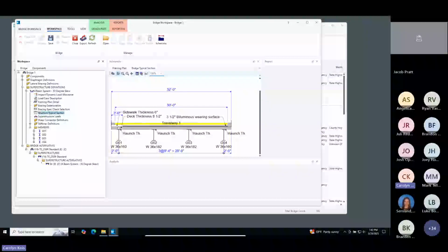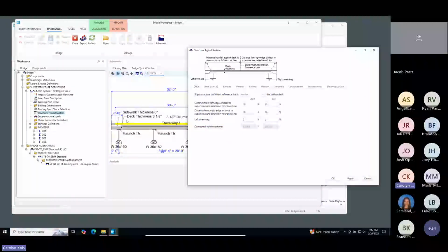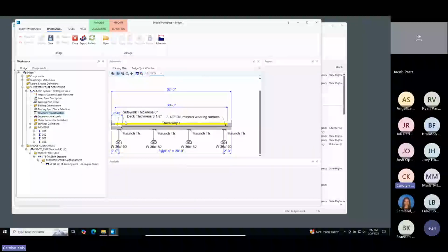So if you put, like, I just put this sidewalk here in the model. I think what the question is kind of getting at is, do you want this travel way set to come up to the edge of this sidewalk or to essentially overlap it, assuming that a truck could actually be there? In terms of the way that this impacts the load rating analysis, it is mainly just going to be where the vehicle is allowed to be positioned when you're running an analysis.